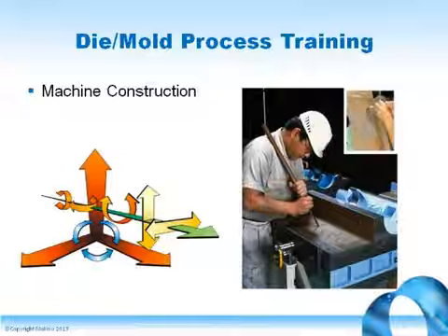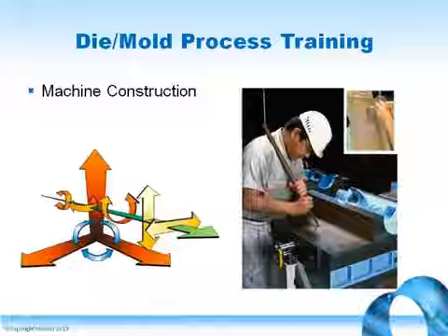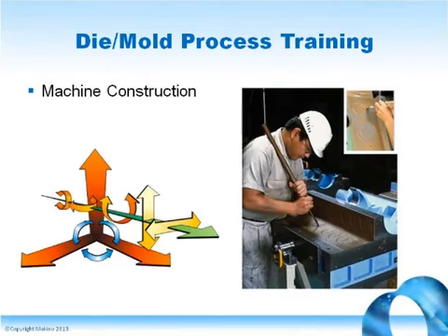Precision assembly. Hand scraping of Turcite-lined guideway surfaces makes for highly precise alignment, exacting surface contact, and lubrication pockets, meticulously matched to mating hardened and ground guideway surfaces, accurate over the entire travel, with tight control over alignment, both static and dynamic, to minimize lost motion and backlash in the guideway system. Extremely accurate, exceptionally stiff and rigid, it makes for an outstanding cutting platform.